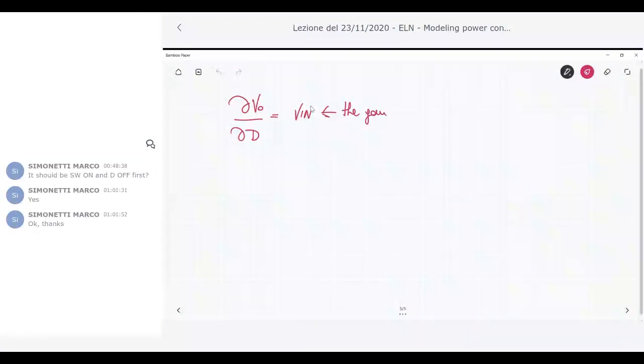Just put your small signal or DC model into your converters, and you can derive all the quantities you are interested in. You can also use this model for analyzing some details of the operation. I want to give you just two short examples that use the pulse width modulation switch network averaging method to define some details that otherwise would be very difficult to find out.